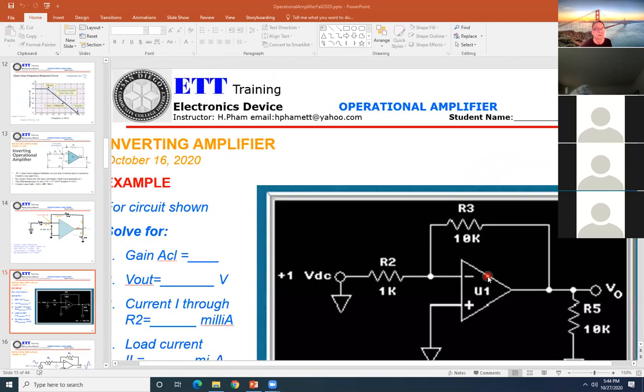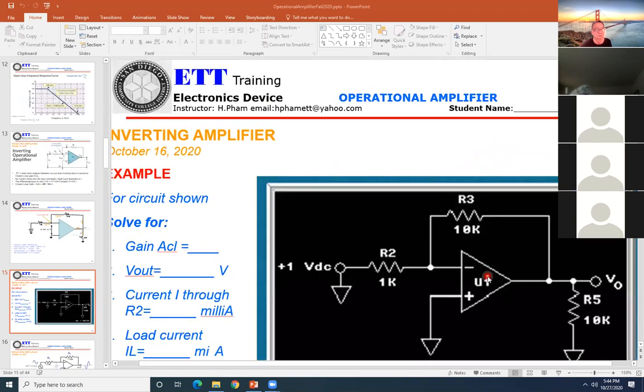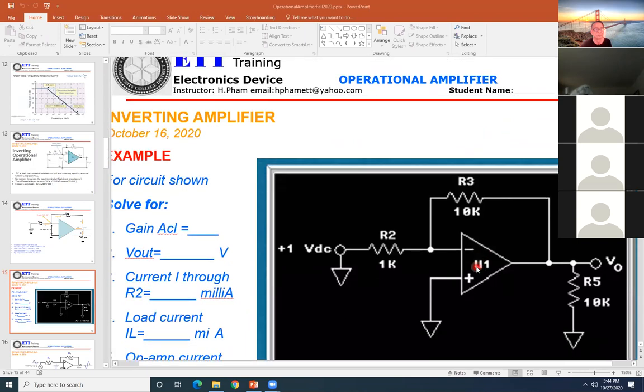So, Mr. Pham, with that example, at V out, that current always stays in that loop regardless of the load that you connect at out. Exactly. That current will never redirect itself to the larger load resistance. No.